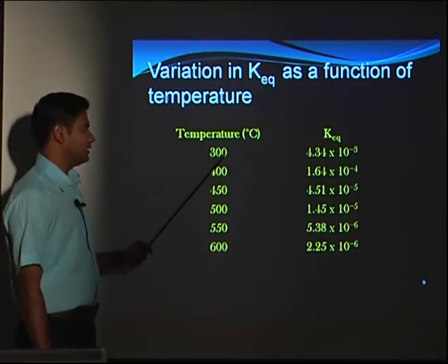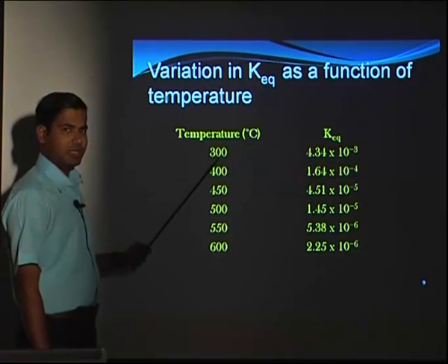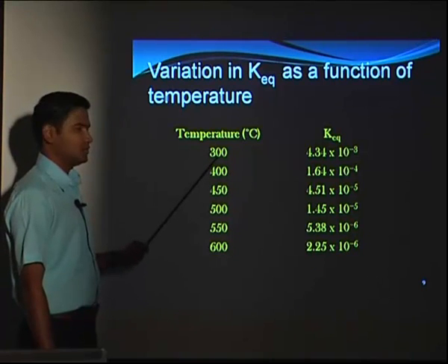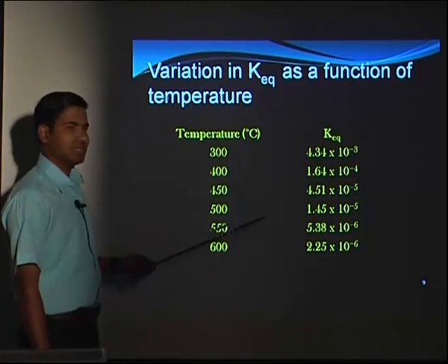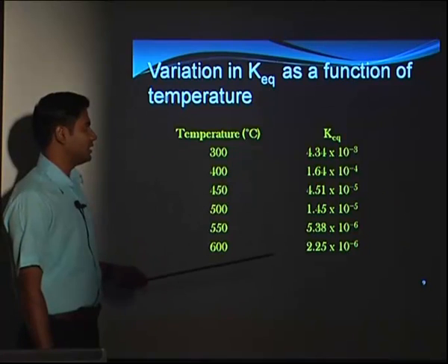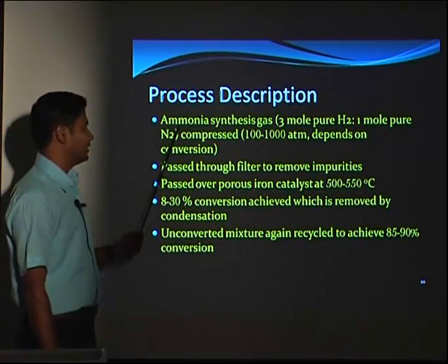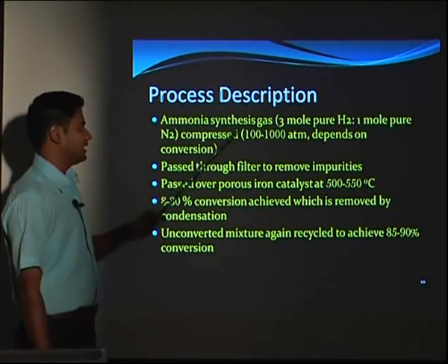So the temperature should not be very low or very high. We should have the optimum temperature. And also the pressure of N2 and H2 should be very high so that the effective conversion is very high to get the ammonia. So here is the ammonia synthesis gas.